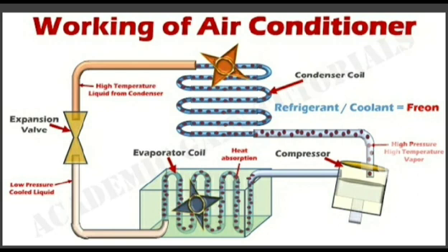The heat energy is absorbed from the hot gaseous refrigerant, and with the aid of the condenser fan, this heat is expelled to the environment. As the heat leaves the refrigerant to the outside environment, it turns back into a liquid. We can think of it as the opposite of the evaporator coil, because the evaporator coils contain cold refrigerant, whereas the condenser coils contain hot refrigerant.